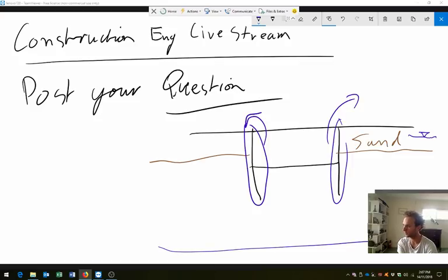Okay, so I'm going to go on to Young's question. So how would we consider a partially reinforced pile? A pile where the cage does not reach all the way to the bottom. That's correct, yes. Or a pile that has less leakages and fewer main bars. So no, a partially reinforced pile is just not reinforced all the way to the bottom. So it might be 5 metres down or 10 metres down or something like that. And that would be done if we were not expecting tension to develop all the way to the base of the pile. But we'd reinforce the top to handle either tension or bending moments in the pile as well.